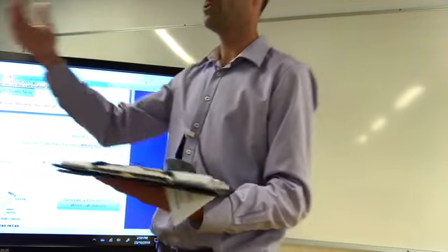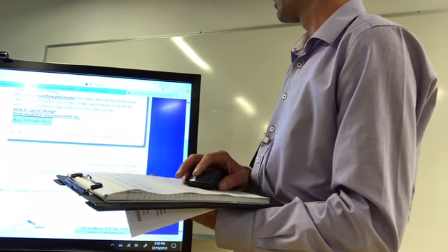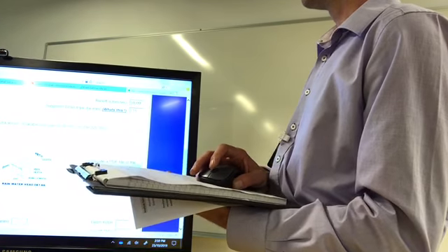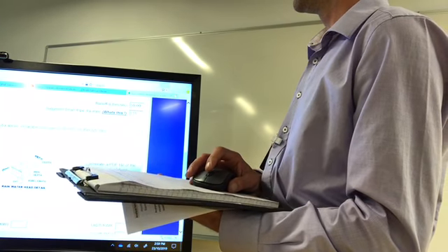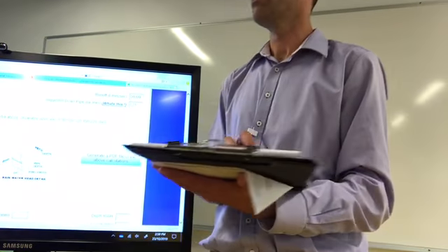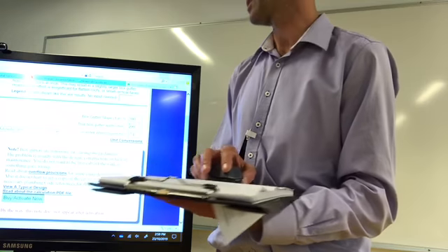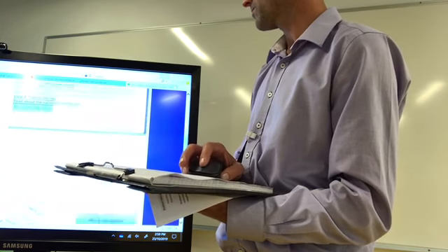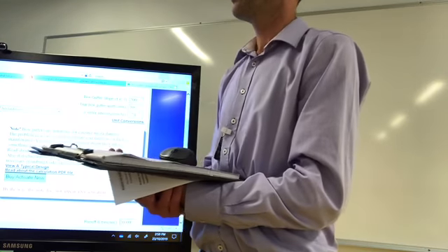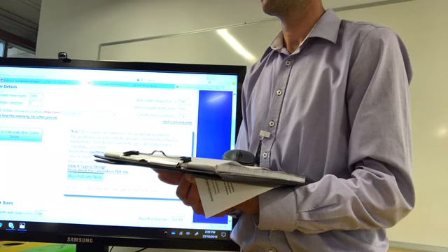So with having 2 downpipes off of our roof, we've got a minimum gutter depth with slope of 140 millimetres and a 300 wide box gutter. That's your minimum size for your parapet gutter.